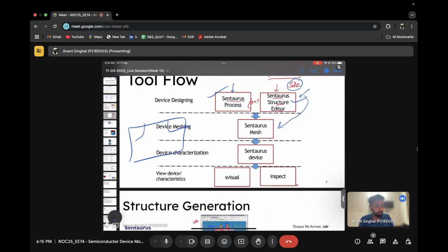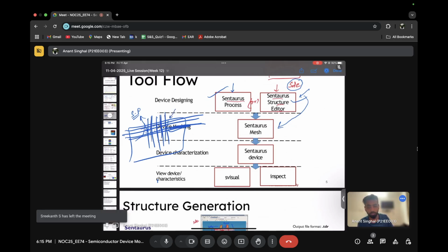What you want is to know the behavior of the electrons in the channel, right? So you divide the device into a lot of parts, and at every intersection you solve the Schrodinger-Poisson equation. That tells you the charge density, the electron density and so on. Dividing the device into small parts is known as meshing. The finer the mesh, the better characteristics you get, because you are solving at more points.